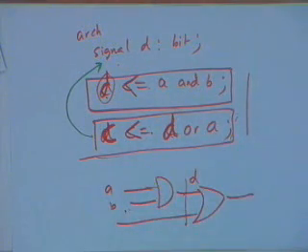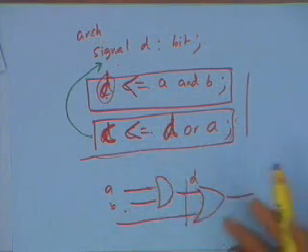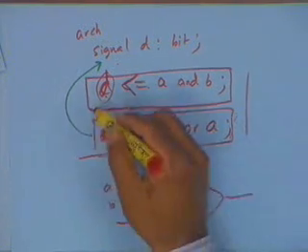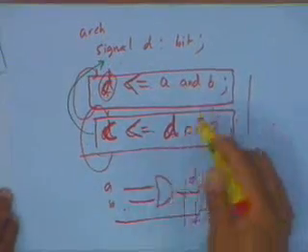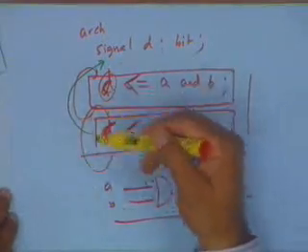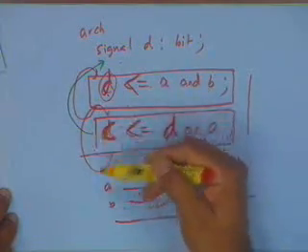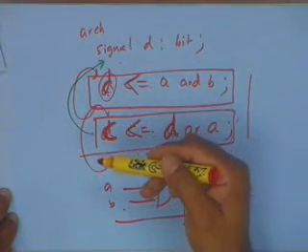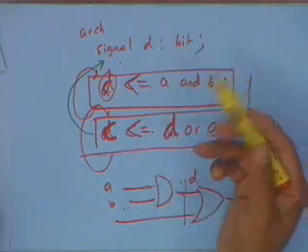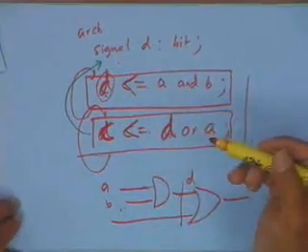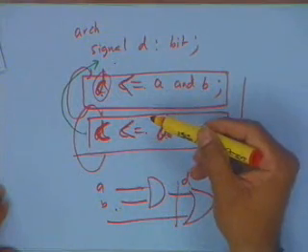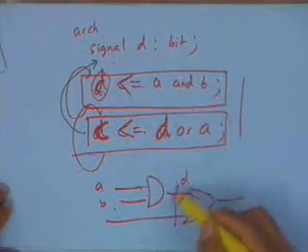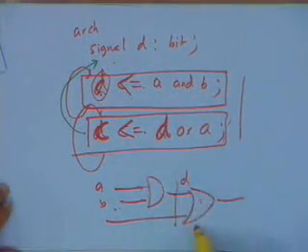So if you write, let's say, 5 concurrent assignments, they are like 5 processes. And they are all active. The implication is this particular statement is being executed repeatedly, this particular statement is being executed. And they never terminate. So what are they communicating? In this case, they will communicate through the shared signals. The shared signals are D. So the output of D is an input to this particular process, and they will be communicating in this manner.